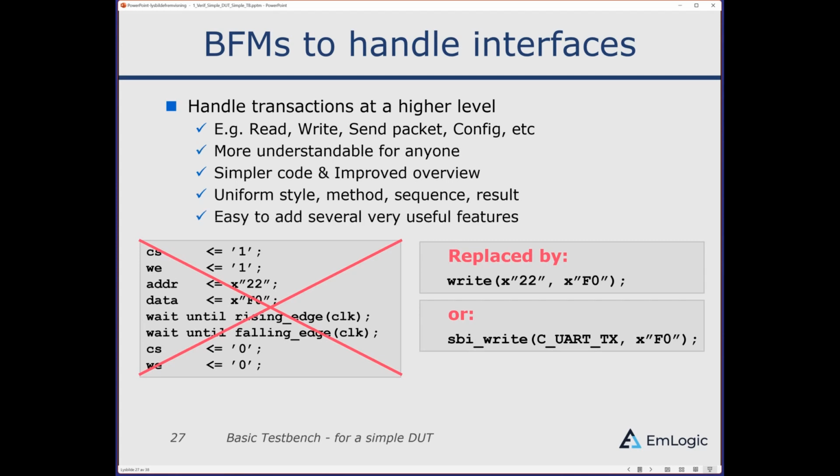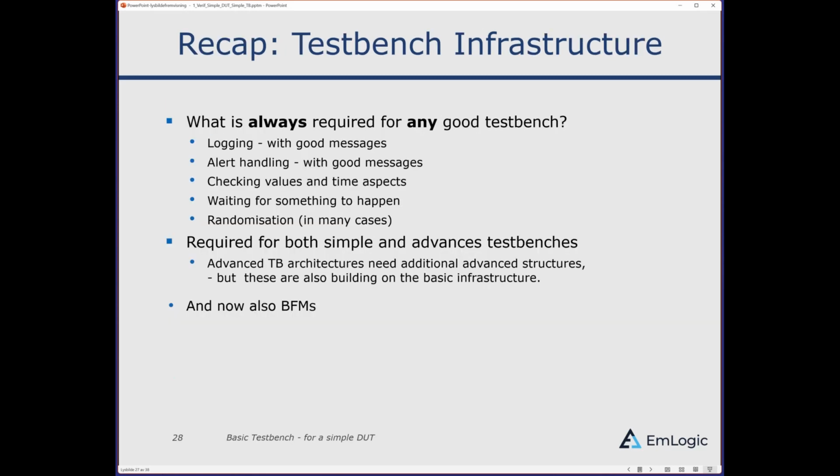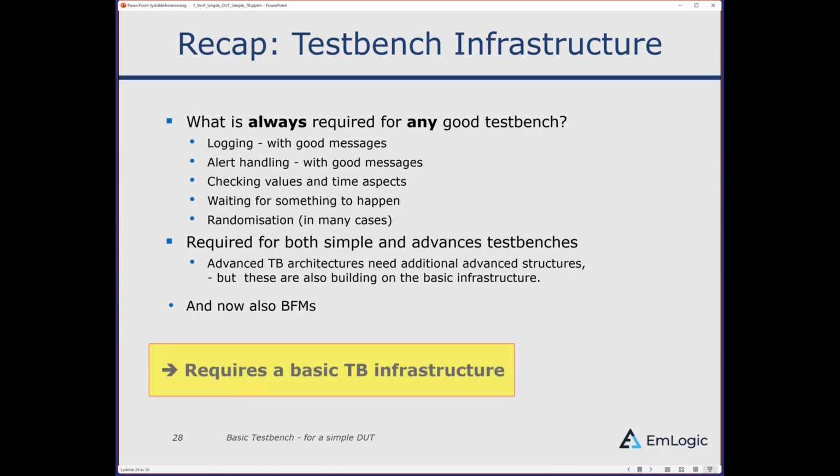Of course, we don't want to do that every time we access a register. And I think everybody today has replaced that type of access with a procedure, a BFM like this, where you just write a write command, for instance, in this case, and the address and the data. Or you could, of course, use any command you like. Since it's an SPI, why not call it an SPI write? Maybe you should use constants for the address, and so on.